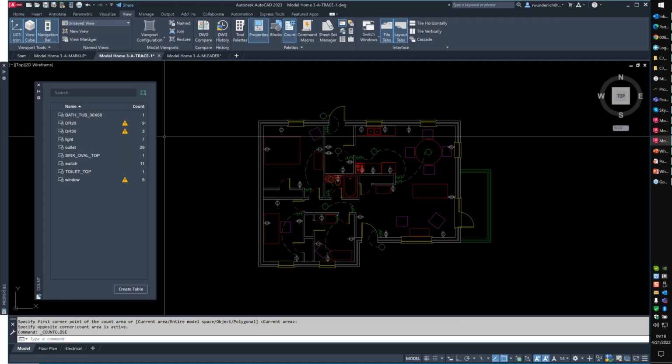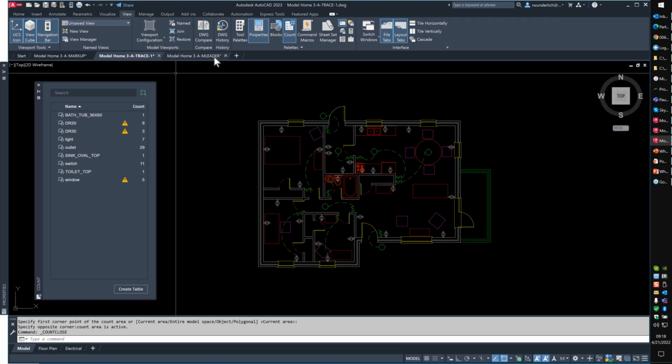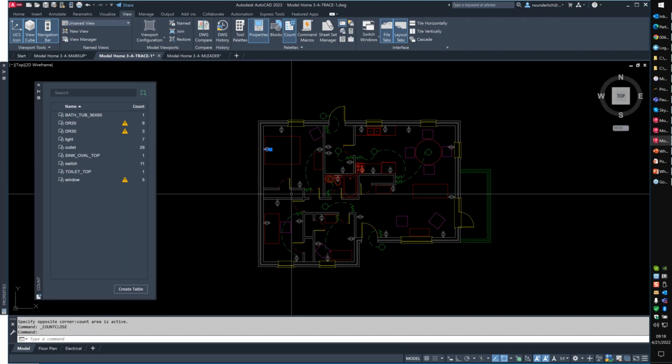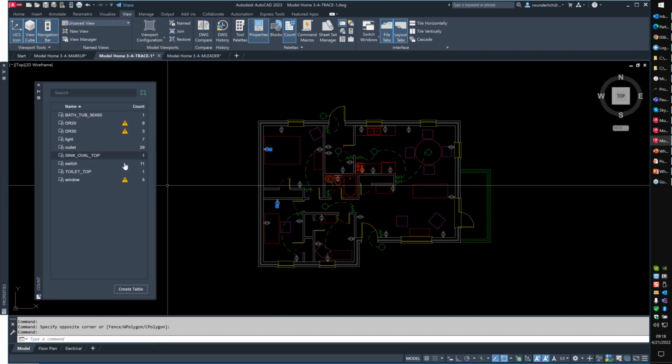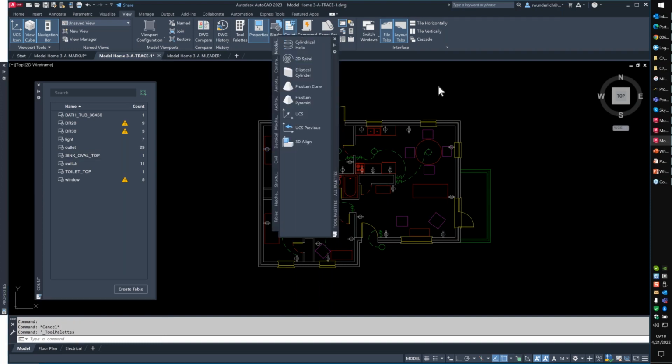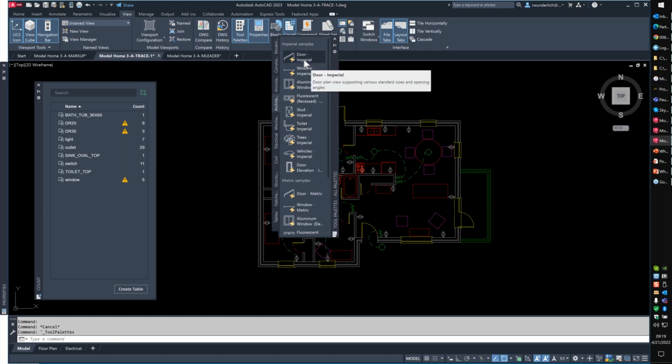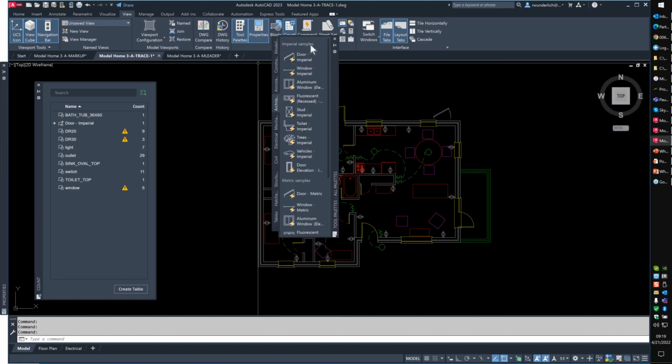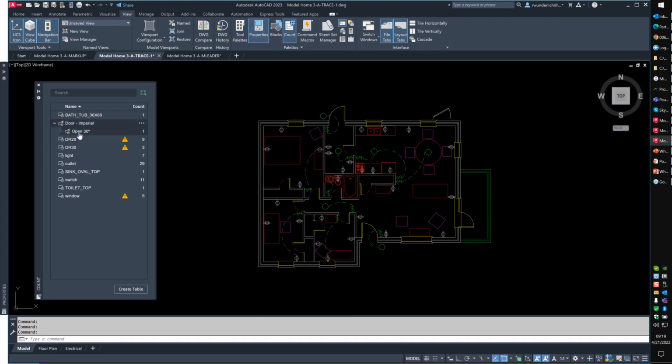Are any of the blocks in the sample drawing dynamic blocks? No, none of these are dynamic blocks. And if you have a dynamic block in here, since now that you've asked, let's go Control 3 and let's bring in a dynamic block. So you're going to see it's a door imperial, and it's going to show you under the door imperial what dynamic block view state it's in. So if I change this to an open 60, now that becomes the open 60 here. Again, this is the same thing we covered last year.